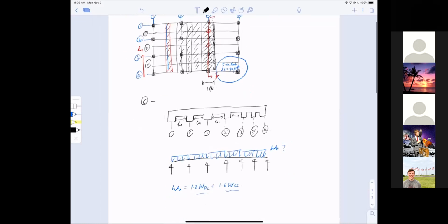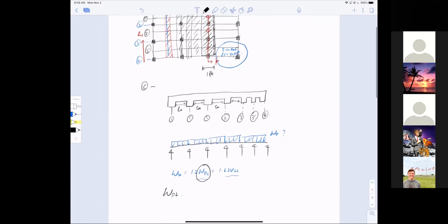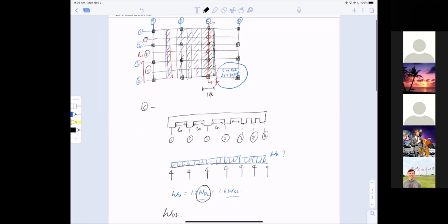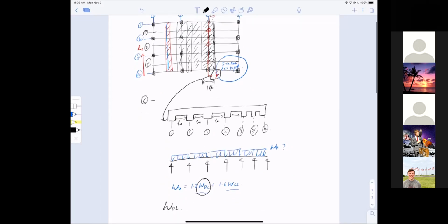If that is known, let's calculate, right? So for the dead load, how do I calculate the dead load? The dead load equals the weight of the 1 foot of strip sitting on top of it. Okay, so be careful now. The cross section looks different. Why? Because now this is what the red looks like when I talk about the span direction. When I calculate my dead load, let me use different color, I have to take a different cut. This is the cut, you see?